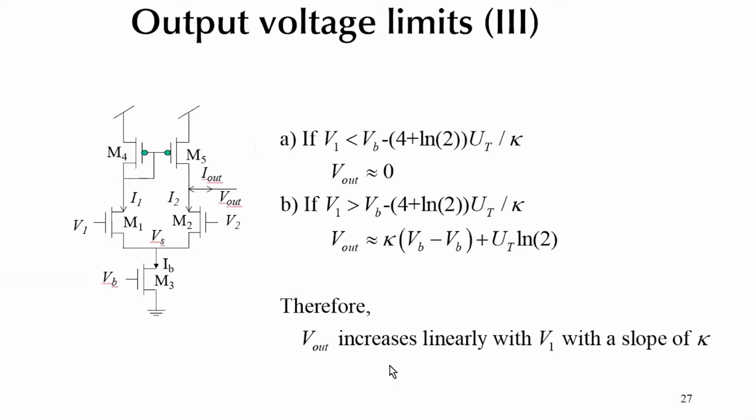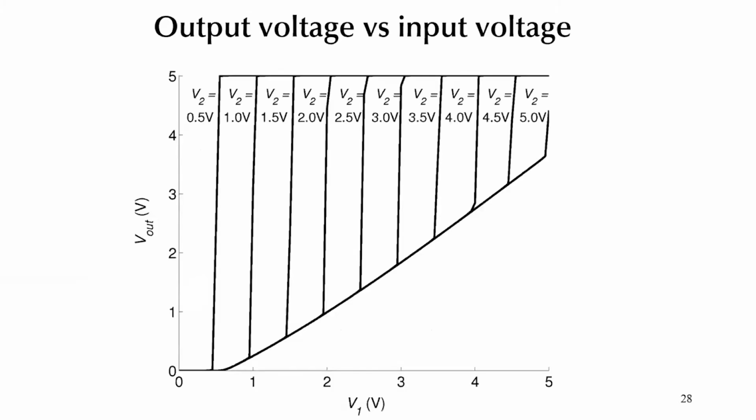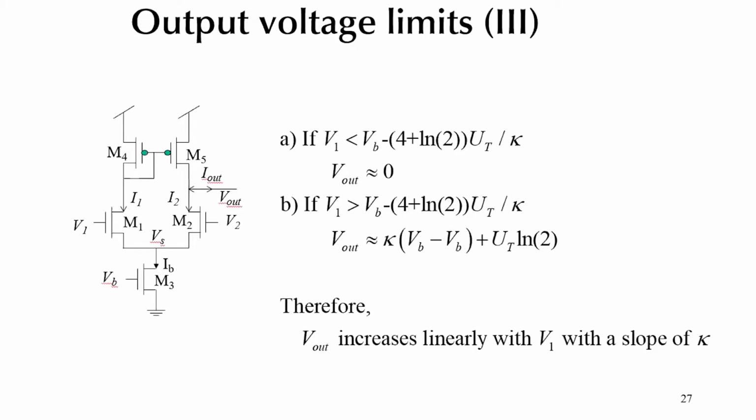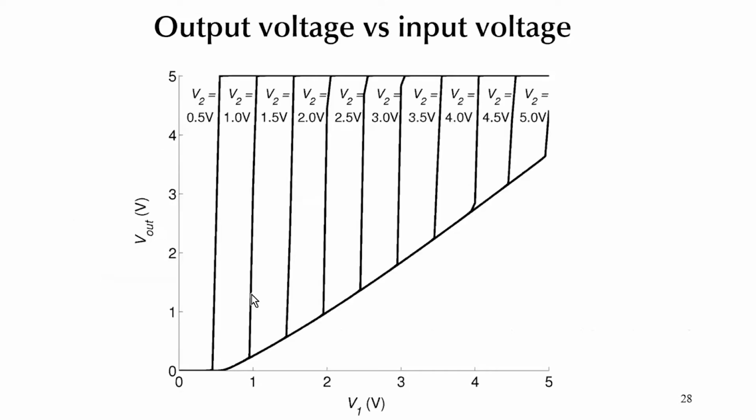It's very difficult sometimes to think about this stuff, right? But it comes because for V out to stay in a certain place, you have to guarantee that all these transistors are in saturation, right? But that doesn't always happen. So as soon as one of the transistors goes out of saturation, then another equation comes into play. And this equation is the one that will give these kinds of curves that you see here, right?